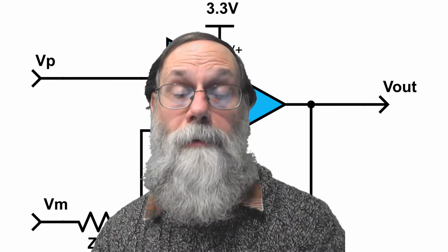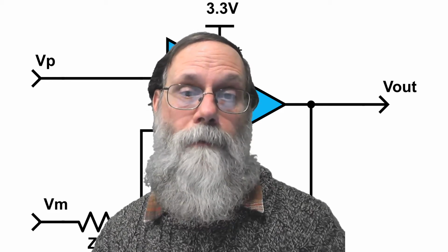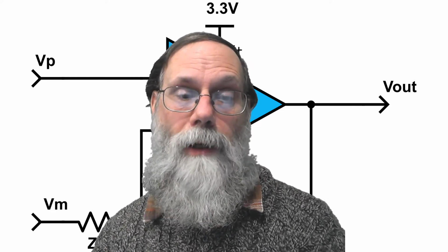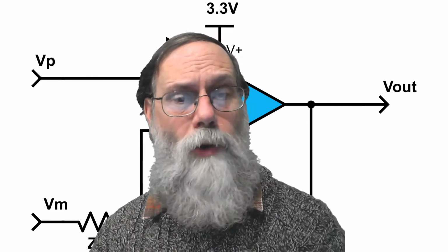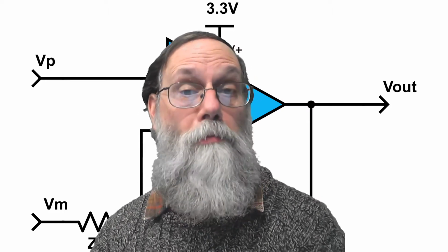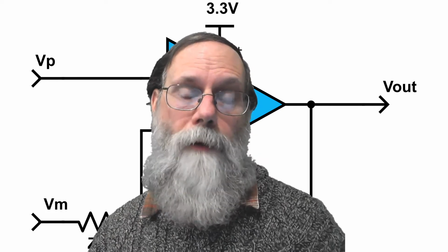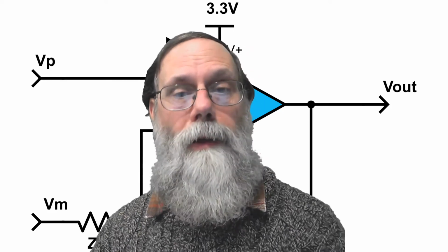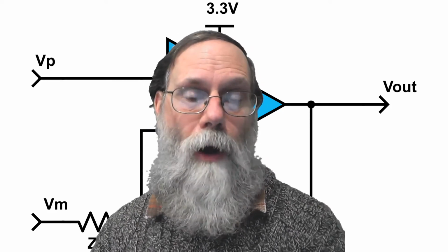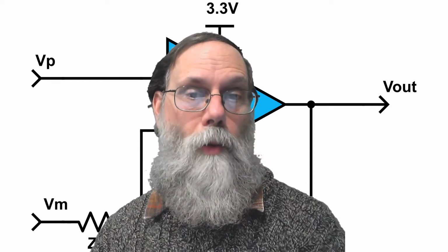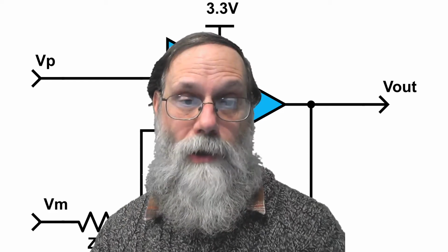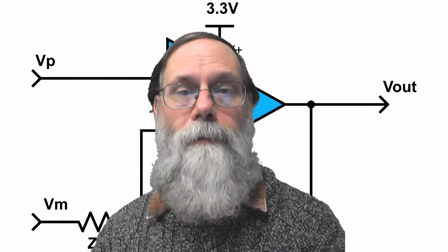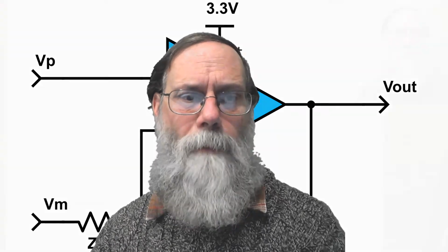This video is about designing multi-stage amplifiers at the block diagram level. It corresponds to section 18.3 of Applied Analog Electronics. Now, there's two main reasons why we go to multi-stage amplifiers. One of them is that we want to get a high frequency amplified, and the other one is that we have DC offsets that would cause us problems with the output range if we didn't deal with them. So let's look at both of these problems with a simplified example.